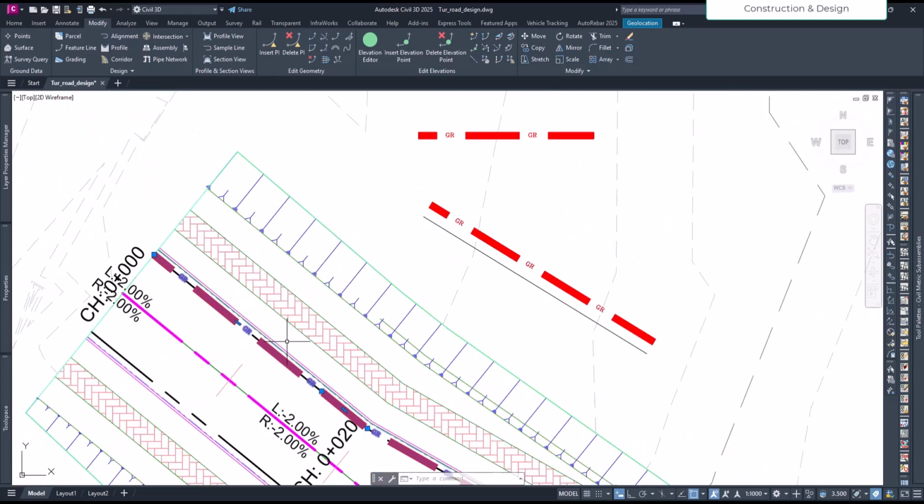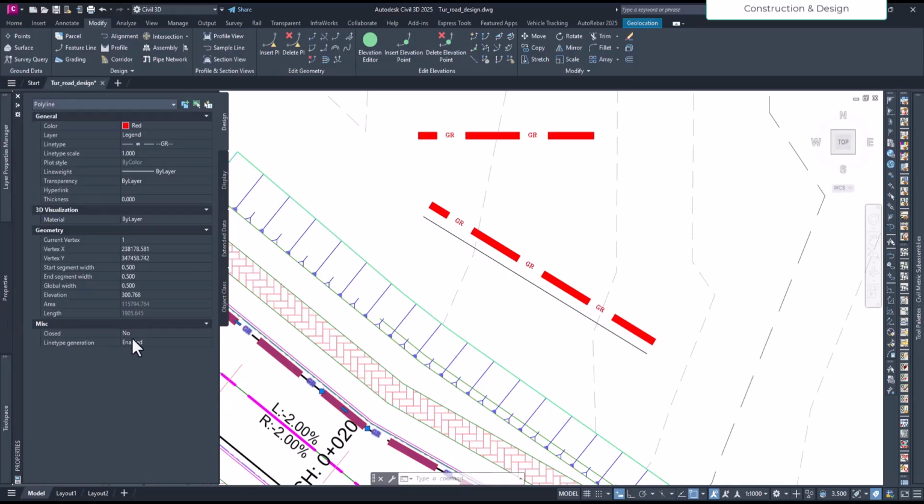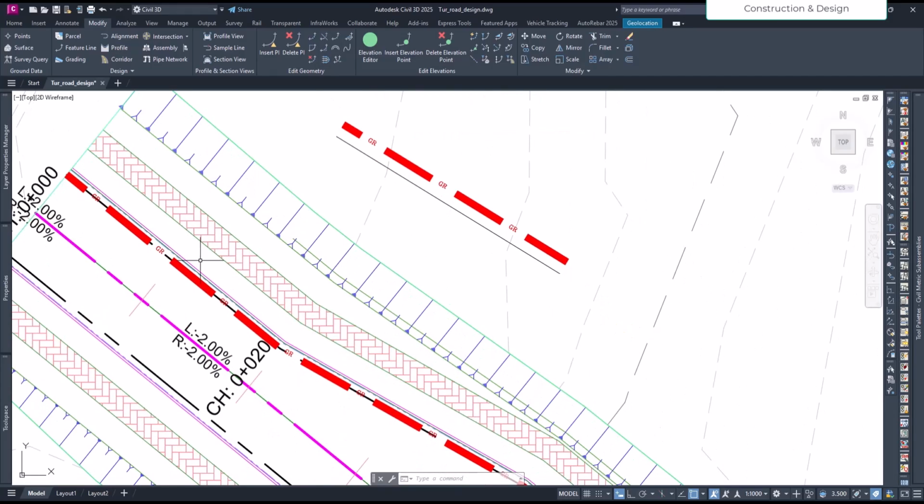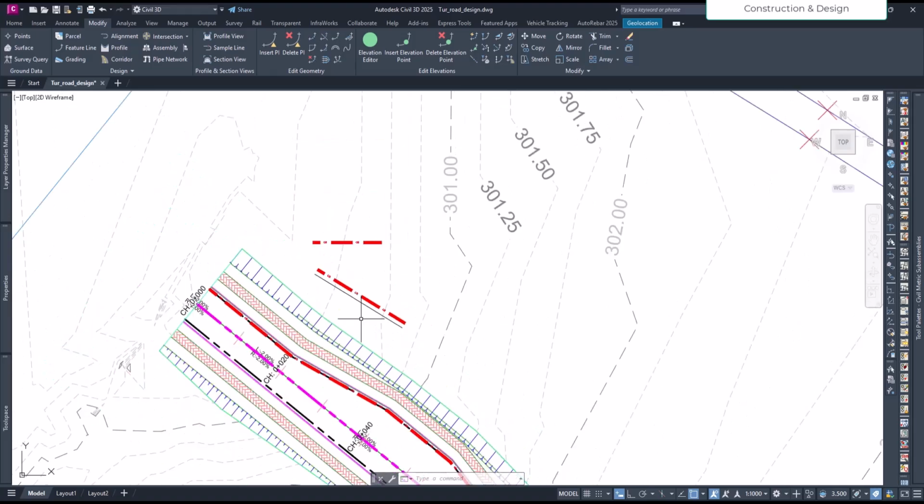But what happens to this particular polyline? If you select it and go to the properties, you see right now the converted one has a single elevation, maybe the starting elevation it has taken. So throughout the corridor, the elevation will be flat, on 2D now. It is now a 2D object. So this is very important to display certain information that you want.